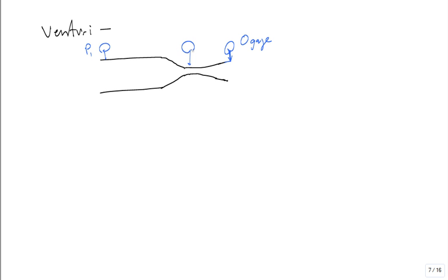Well, right here we have a throat. So what is the pressure right here in the throat, the smallest diameter, before you open it up some? Well, isn't that going to be a low pressure? So tell me a little bit about the pressure at state 3 and the pressure at 2. Forget about 1 for a minute. Just compare 2 and 3. If 3 is atmospheric pressure, what about the pressure at 2?